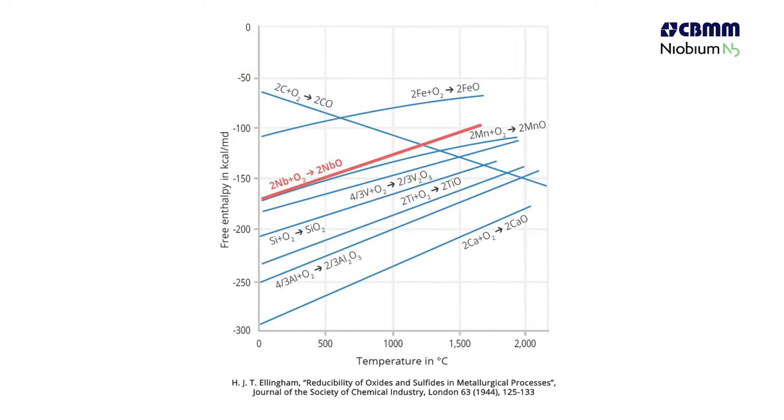The Ellingham diagram is widely consulted to determine the optimum sequence of additions of the various ferroalloys, and aluminium as a powerful deoxidizer. Ferroniobium is only added when the strongest deoxidizers, like aluminium and silicon, have done their work, but it can often be just after, or in conjunction with ferromanganese.